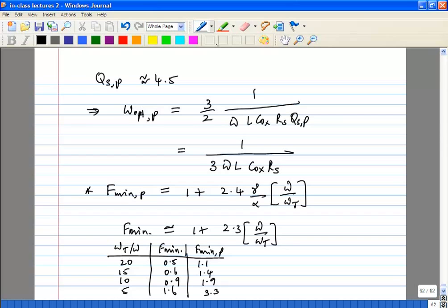You can see that as long as you choose a properly normalized omega T or omega. So where does your power come in? Power comes in through your omega T. If you burn more power, you can actually get better omega T's, if you have control over the width and the current consumption. So you choose omega T based on that.